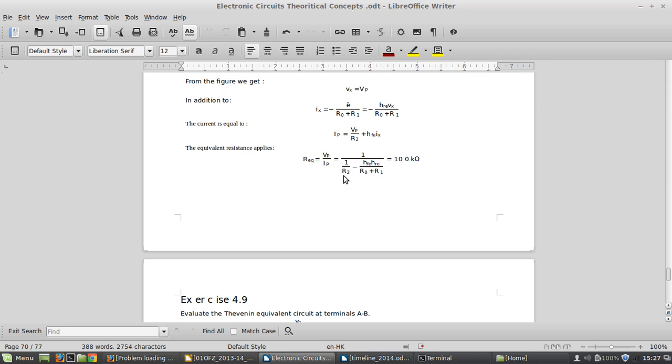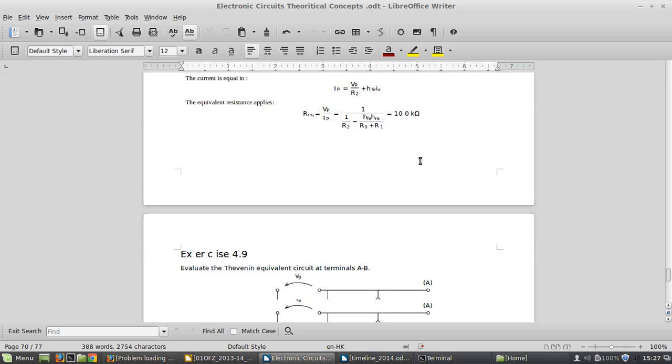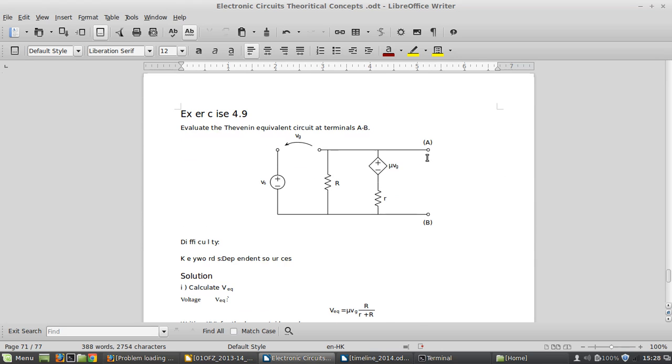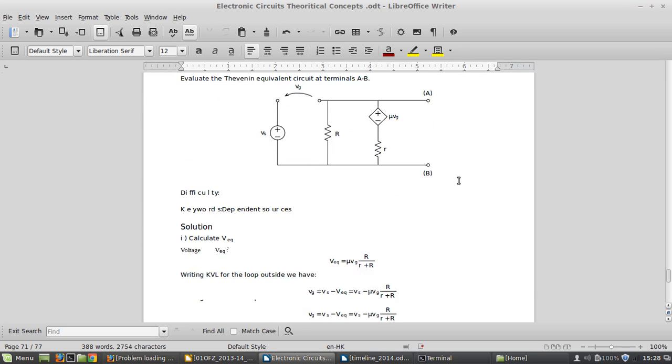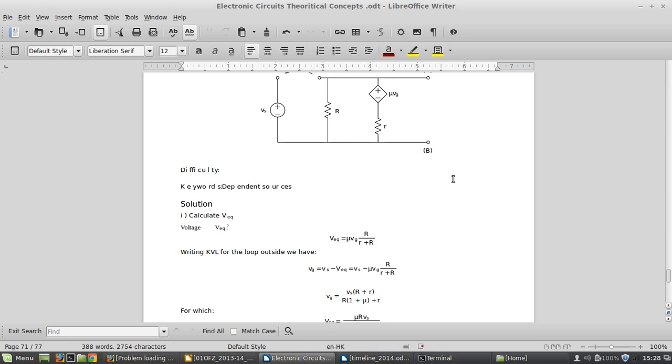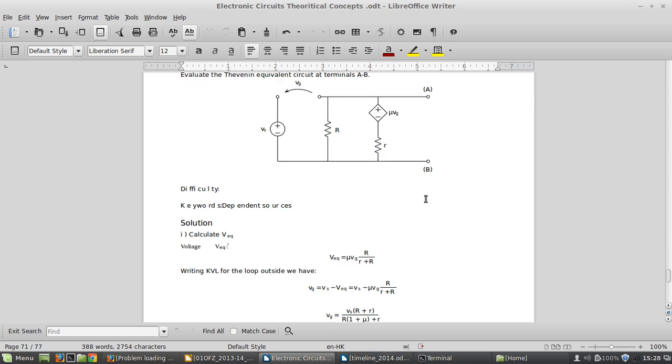They have no contribution, so having no contribution I can turn off this independent source. So I try to solve this portion of the circuit. In this portion I try to find the value of Ix, and Ix will be just this dependent source voltage value divided by the total resistance present in the circuit. So similarly I find the value of Ix, and this value of Ip.